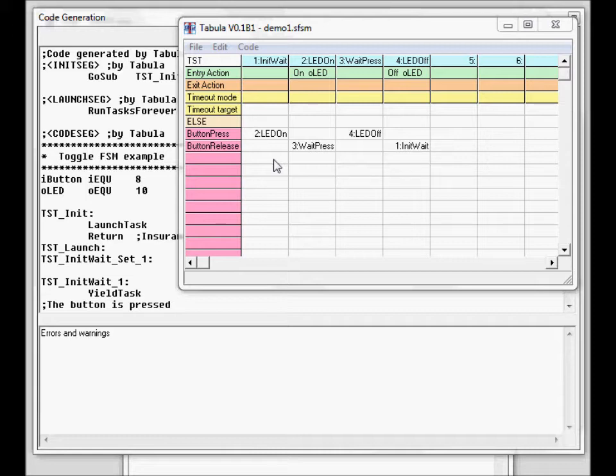But what of course we discover is that people forget to turn the lights off. So we decide that we want to put in a timer. Now where would we put the timer or timeout? It would have to be in state 3, because this is where the light is on and waiting for the second press that presumably is never going to come.